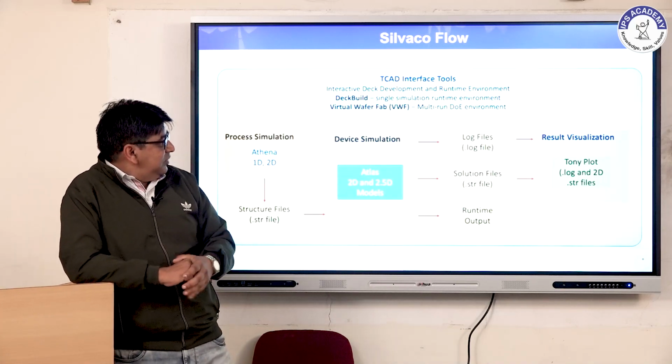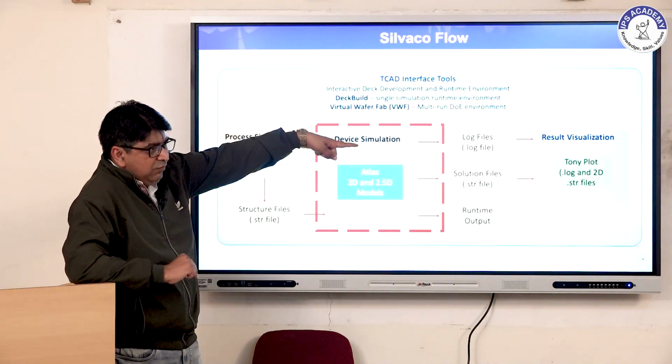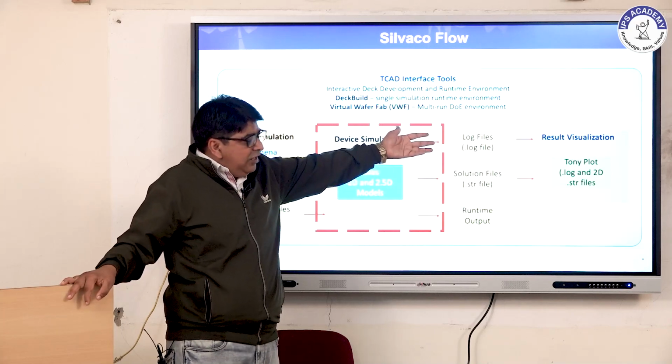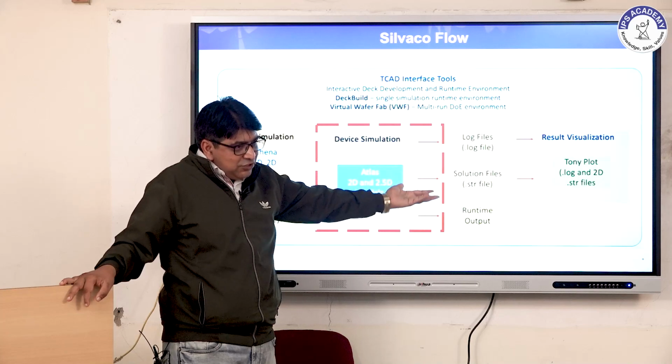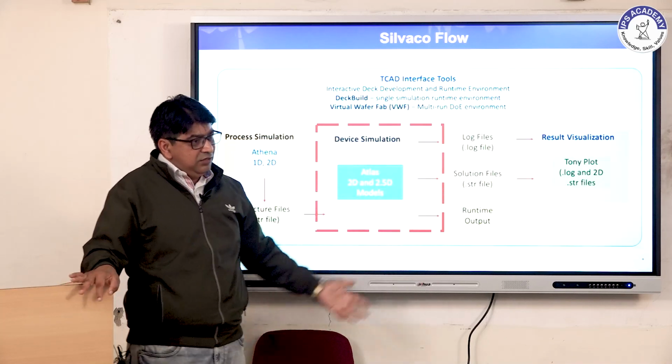Okay, come to the next one. That is the same thing I discussed, about only the Silvaco tool. Once you do the device simulation, it will generate a log file that contains the data, and you can plot it in Visual TCAD, and it will generate the structure, the .str file. The file format is important so that you can understand what you are going to do.